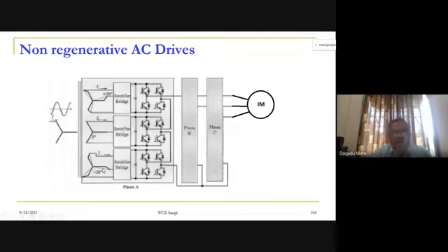Again here we have a 3-phase transformer, primary star connected, and we have 3 secondaries. One secondary is star connected, another secondary is what is called a zigzag type connection. Extended star you can call zigzag. This connection you have studied, this is a zigzag connection. With the help of that we can obtain a phase shift of 20 degrees, plus 20 degrees and minus 20 degrees. And here we are using these rectifier bridges, diode bridges. They are not connected in series, they are separate.